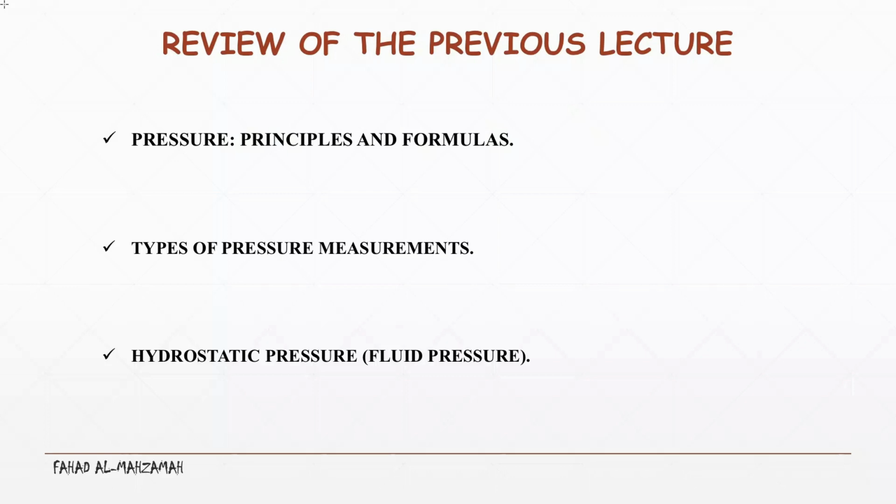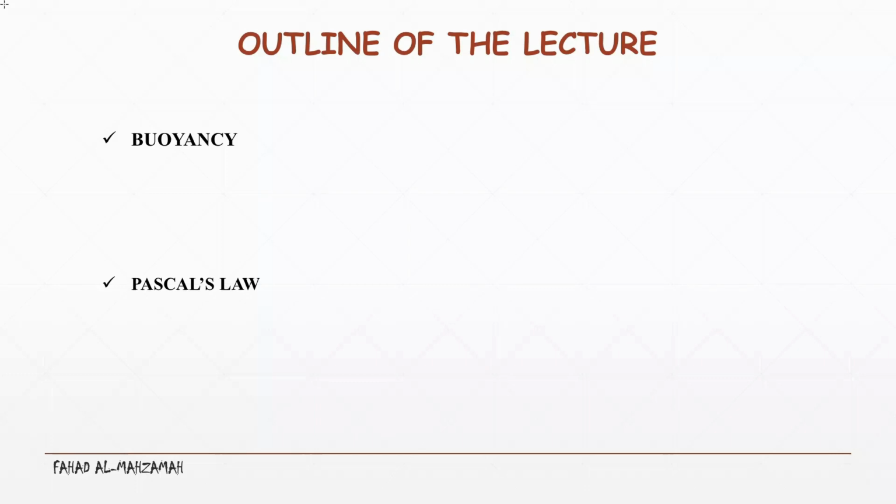liquid pressure, and we concluded about hydrostatic pressure that the liquid pressure is dependent only on the type of liquid and the height of the liquid. So it's independent of the shape of the container, regardless of the weight of the liquid, and again regardless of the volume of the liquid, as long as the type of the liquid, which is expressed by the density, and the height of the liquid are the same, so the pressures are the same.